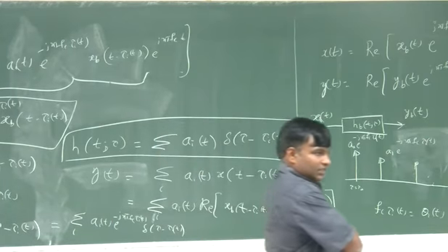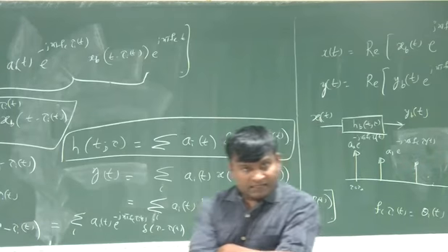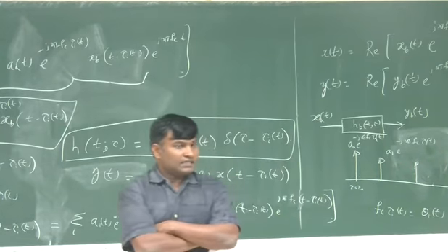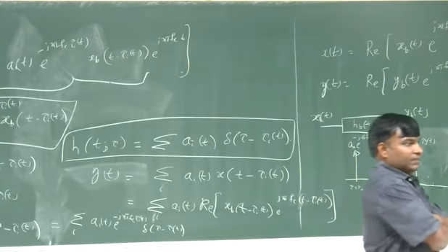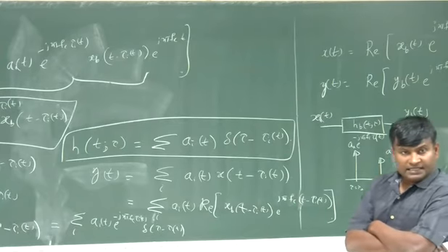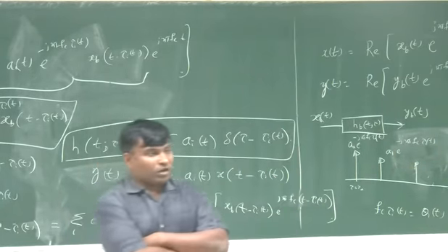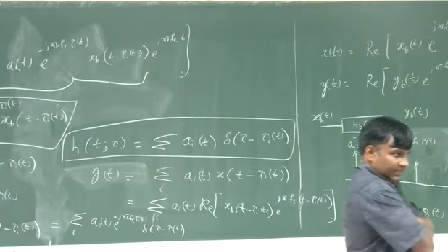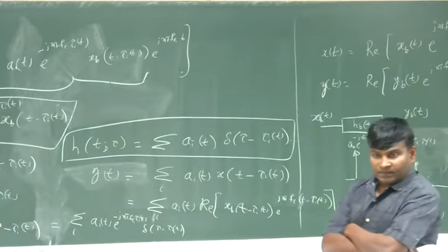What we are going to do is take the baseband signal, apply a low pass filter and take samples at the rate 1 over T, where 1 over T is the baud rate of the signal. 1 over T is intimately related to the bandwidth of the system. In the Nyquist class of signals, 1 over T is indeed the bandwidth of the system. If you don't want to operate at 1 over T rate, you can operate at 2 over T or 3 over T or some other rate in between.